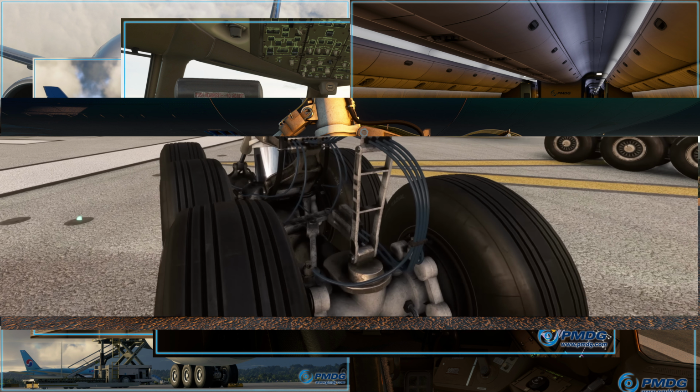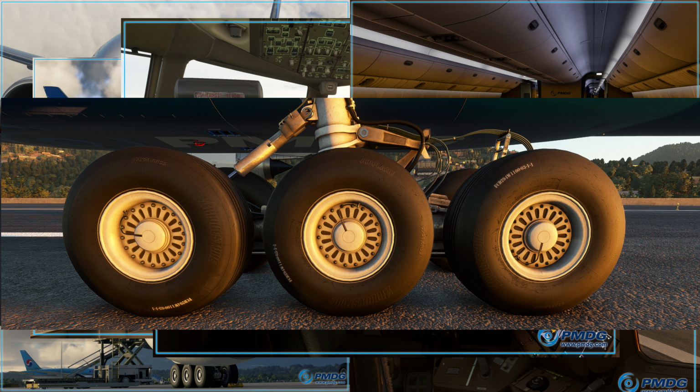Now, the landing gear trucks included in the 777-300ERs have a unique cantilever function which is fully modeled. That function causes the truck to lock in place during takeoff and use cantilever action to provide additional tail clearance during rotation. You can basically imagine this like the gear is angling upwards, so the aft part of the gear is pushing the entire airplane a little bit upwards, providing additional tail clearance during the takeoff that helps to prevent a tail strike. Of course, that is fully modeled in the PMDG 777.